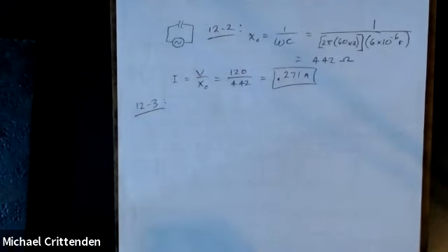Well, the reason this is here is just to illustrate an important difference between resistance and reactance. Resistance is a fixed property of the resistor. Unless you do something like overheat it, we saw in one of the labs a while ago that resistance changes with temperature. But unless you overheat the resistor, a 442 ohm resistor is a 442 ohm resistor, end of story. A resistor doesn't care if the frequency is 1 hertz or 1,000,000 hertz. The surrounding material gets in the way of the flowing electrons to the same extent.